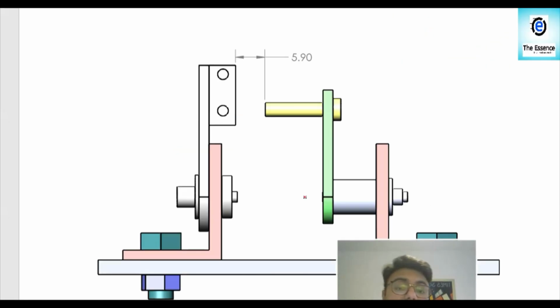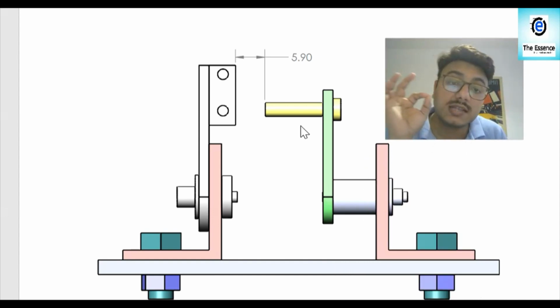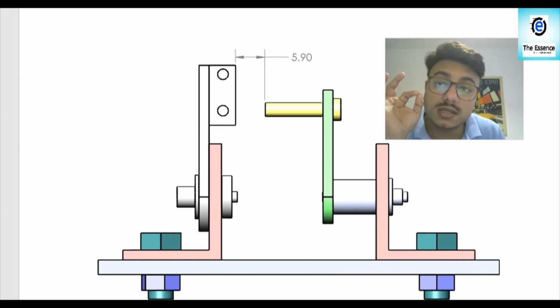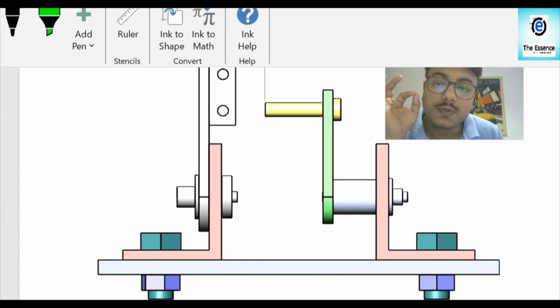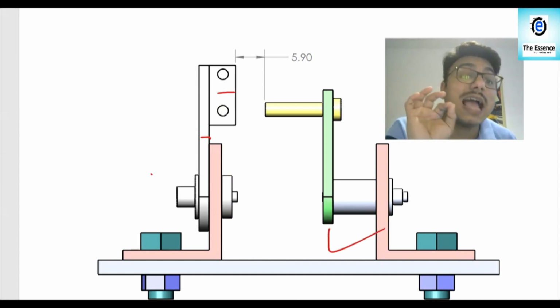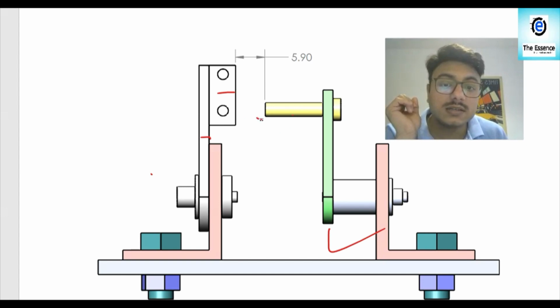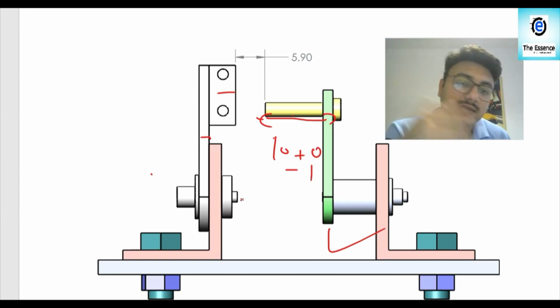Now in this case as well, if you go and measure the mean gap, remember that all the dimensions of these parts, whatever we have taken, should be at their mean. Suppose in your CAD this dimension over here is like 10 plus side 0, minus side 1, something like this, just random.